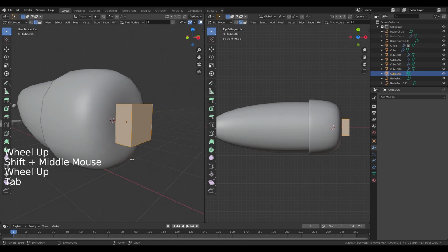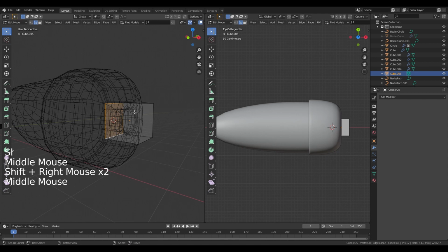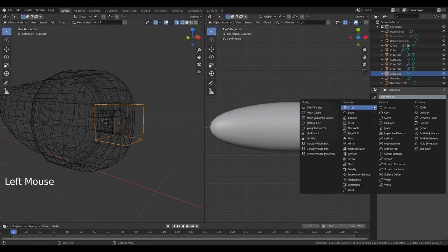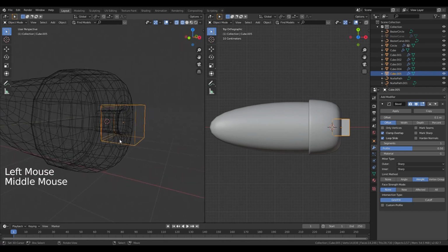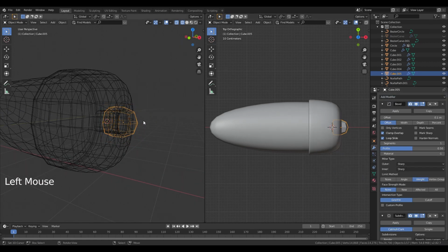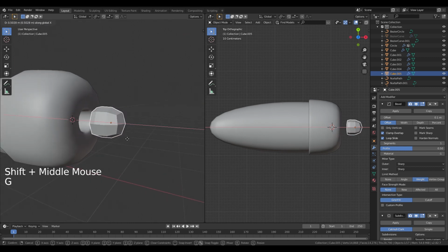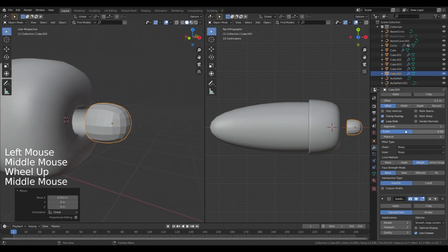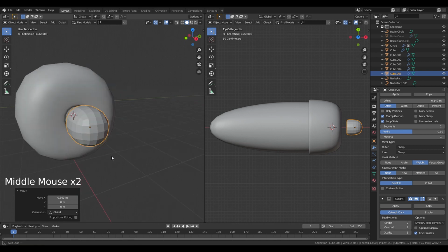I need to have a sort of conical shape. So I'm just selecting the back faces. Again, going into mean bevel weight and adding a bevel modifier, which is going to work from weight, like so. I'm going to add a subdivision modifier. Now let's go into solid view. I'm just going to move this on the X-axis like so. Increase the subdivisions so I see a bit better what's happening, and maybe increase the segments. Offset, maybe I can put the offset to 0.15 like so. Shade smooth, and that's it.